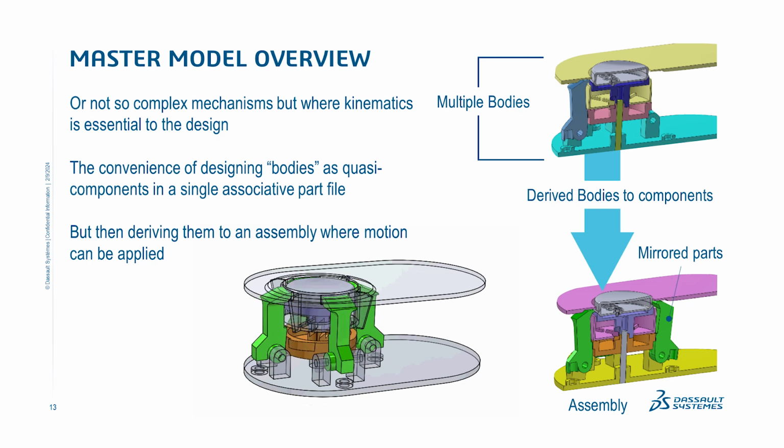And then the idea is that once you derive those parts out using save bodies or insert part, those parts become immune from their associativity. That is, you're disassociating the association of those parts to each other from motion. So once you derive them out, create it into an assembly, then you can apply motion mates to that and do everything you want to do, but still maintain the design intent of the original parts. So I love to use it for that.